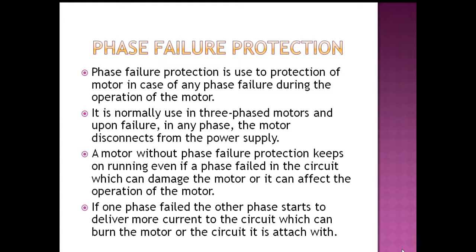Next is the phase failure protection. Phase failure protection is used to protect the motor in case of any phase failure during the operation of the motor. It is normally used in three-phase motors and upon failure in any phase, the motor disconnects from the power supply.